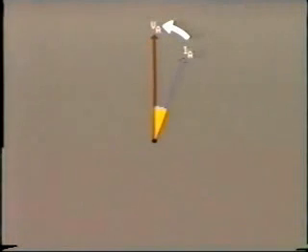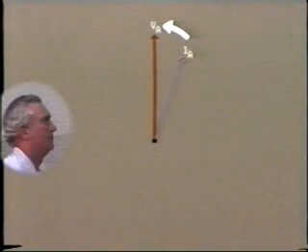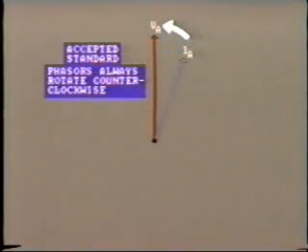This angle between voltage and current represents the phase angle displacement. In this case, the current is lagging the voltage. We know this because this arrow shows us that the phasors are rotating in a counterclockwise direction. And from our position in space, we will see the voltage phasor before the current. You may occasionally see the arrow indicating clockwise rotation, but normally the arrow is not shown because the generally accepted standard is that phasors always rotate counterclockwise.